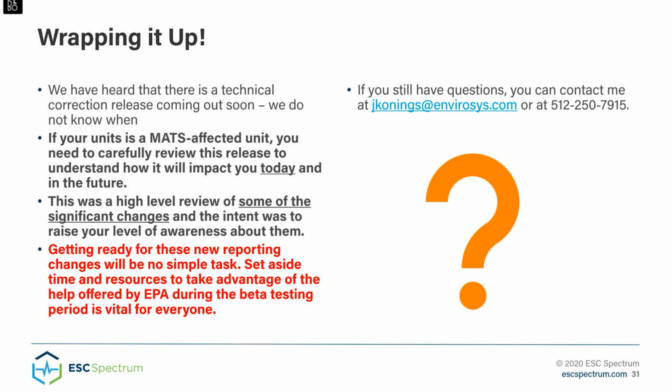The next question is, will the quarterly reporting replace using ECMPS to submit stack testing results? Yes, yes. The various sections in Appendix E do contain the elements that the EPA requires that you submit for the stack testing data and results. And so, yes, Appendix E will become the required method for submitting stack testing data electronically into EPA.